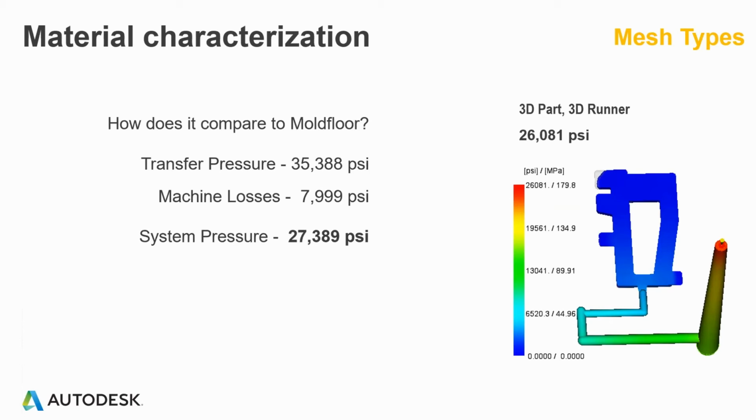I'd add one more thing here. Some of you that may have seen pressure losses out of a machine from a pressure drop study or something, which we'll speak more about at the end, may think 8,000 is quite high. Commonly, I would agree in a reciprocating screw molding machine. However, this particular machine happens to have a long nozzle adapter on, so we frequently will see pressure drops anywhere from 6,000 to 10,000 PSI just to get material out of the molding machine nozzle under the process conditions.